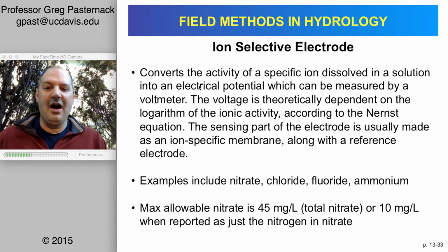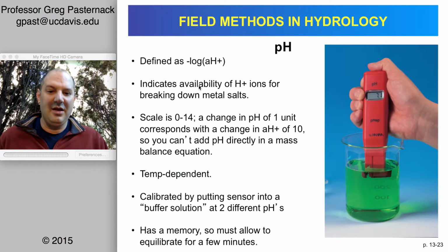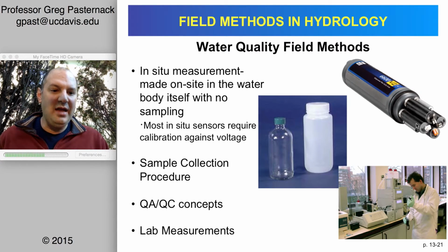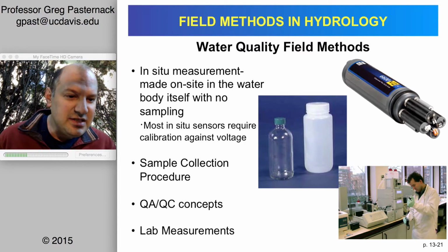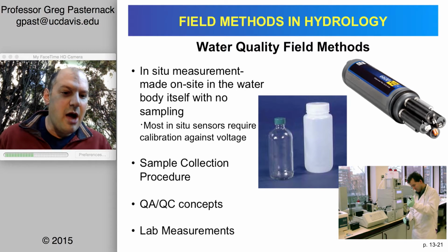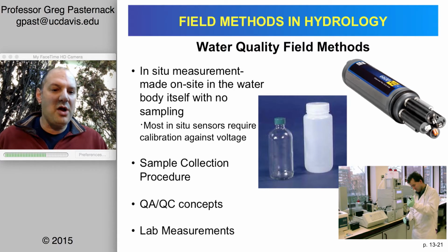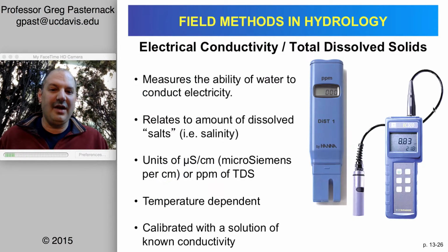And if you look back at the first slide of part 2, let's see if I can go back real quick. In the upper right, I think some of these are turbidity because these have these wipers on them, but you can see a variety, actually six different little sensors sticking out here. So you have one data logger. This whole thing could be placed underwater, and then each one of these could be a selective ion electrode, or it could be a turbidity or temperature or whatever kind of sensor.